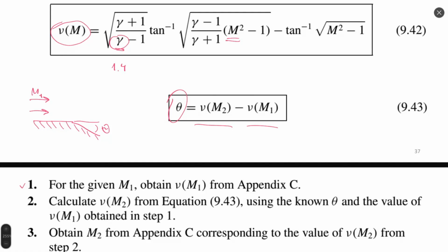If we have so many definitions of the adiabatic constant, we can use a different approach to determine it. So there is not just one way to determine gamma. But that's another story for another lecture, probably, and then we can return to our Prandtl-Meyer flow. So once we have the M1 flow which enters and the geometry is still constant, then we use appendix C or we use equation 942 and we obtain a new Prandtl-Meyer function.